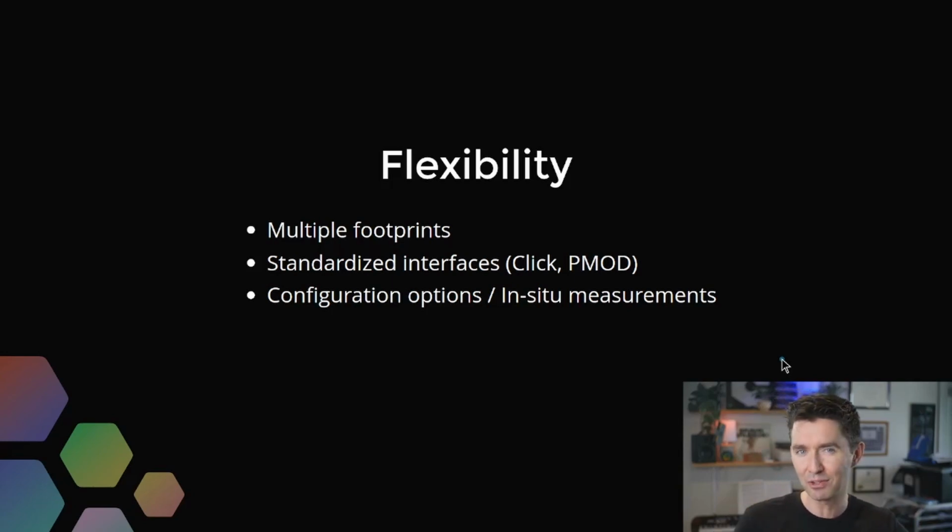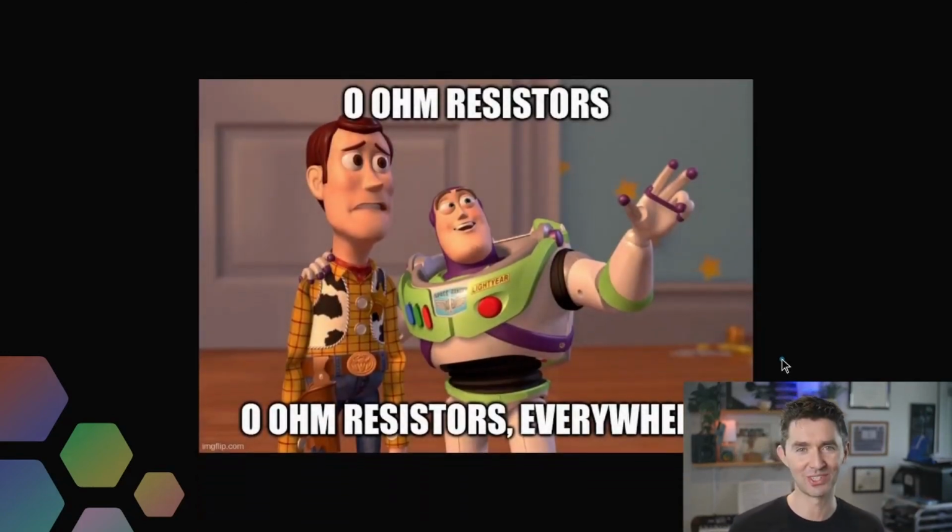And then I put configuration options and in situ measurements, and this is an abstract way of saying 0 ohm resistors. I love 0 ohm resistors. I put them all over my board. Oh man, my face is blocking. That says everywhere, of course.